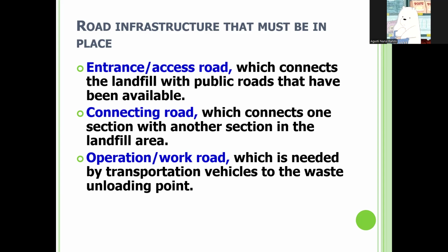So for the road infrastructure that must be in place, the first one is the entrance or access to the road, which connects the landfill with public roads that have been available, and then connecting road, which connects one section with another section in the landfill area. And the last is operation or work road which is needed by transportation vehicles to the waste unloading point.